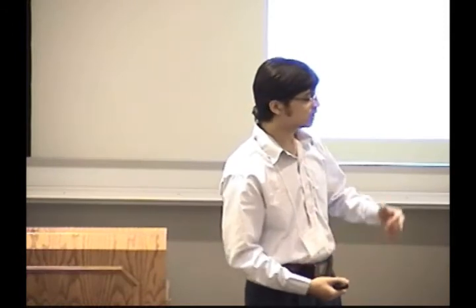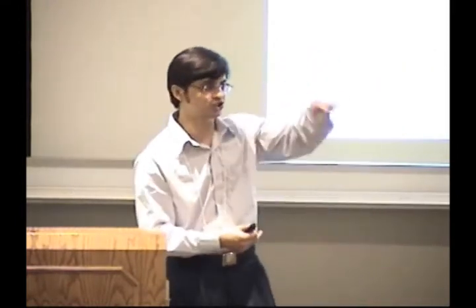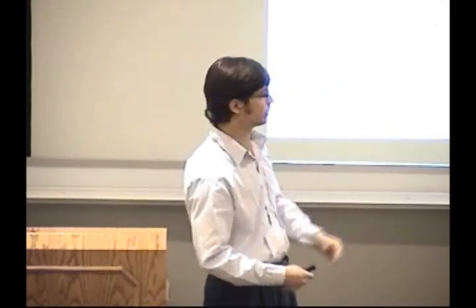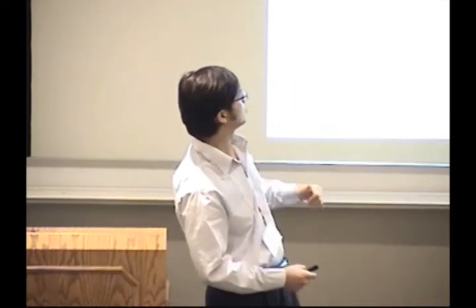Just to give you an example, a mirage that you see on hot days is essentially a density gradient between the hot air on the bottom and the cold air on top. So an image you see through the mirage is basically a first gradient of the density that you see as a shimmering. Schlieren is the second gradient. It gives you some more information about the density fields. I'll go into some images later on that might be clearer.